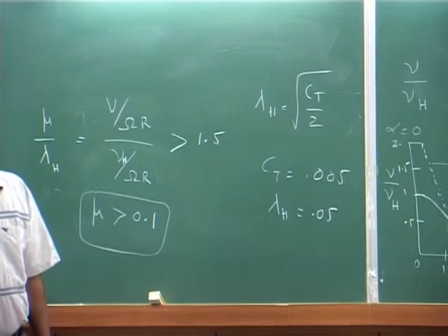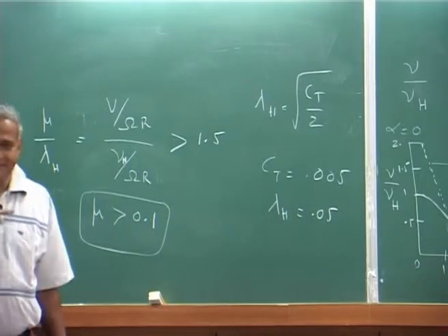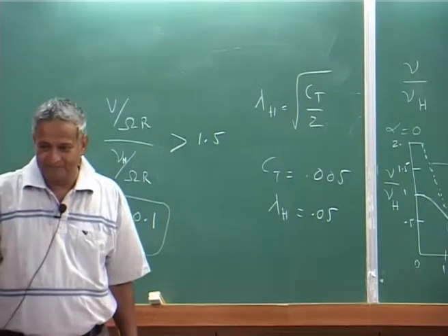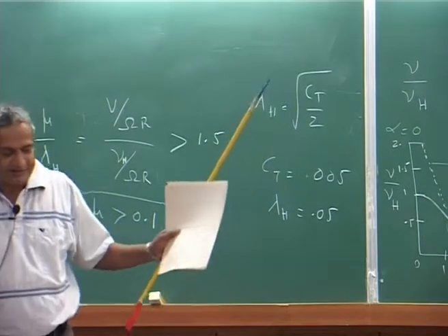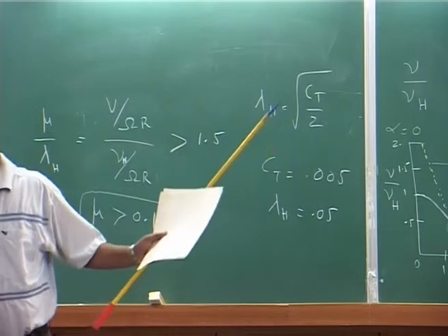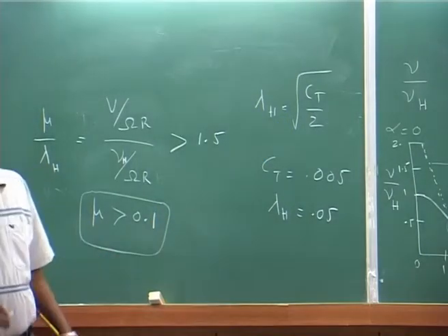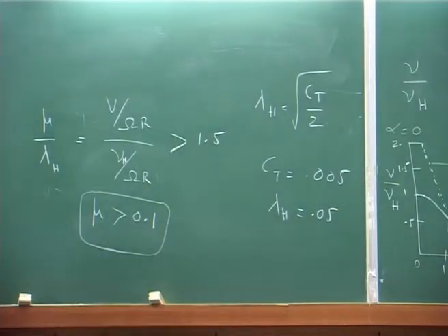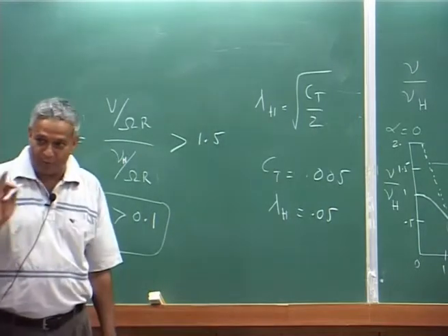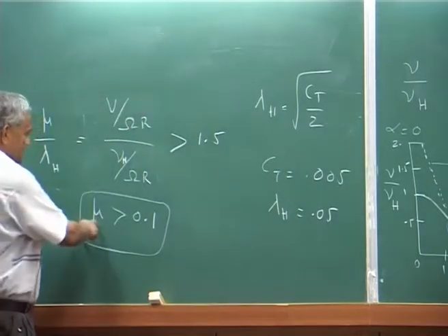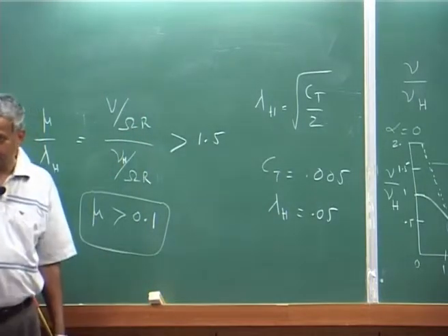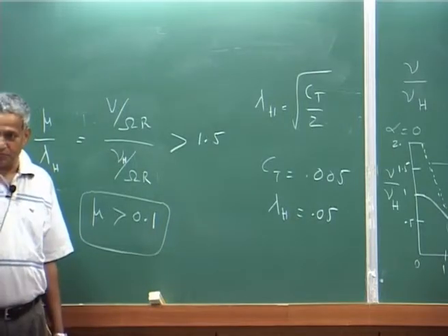Okay. Then you can use the high speed assumption for inflow. The rotor basically behaves like a circular wing. Reasonable. But in between 0 to 0.1 in the forward speed, because this is forward speed advance ratio, in the range 0 to 0.1,